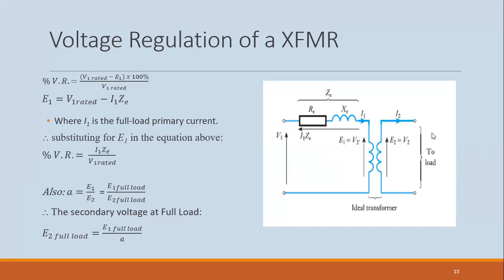So the capacitor could supply the load and reduce the demand coming from this side of the supply. But the transformer now is an enclosed device, so it would be inside a container, so you wouldn't be able to go on and connect a capacitor across it like that.